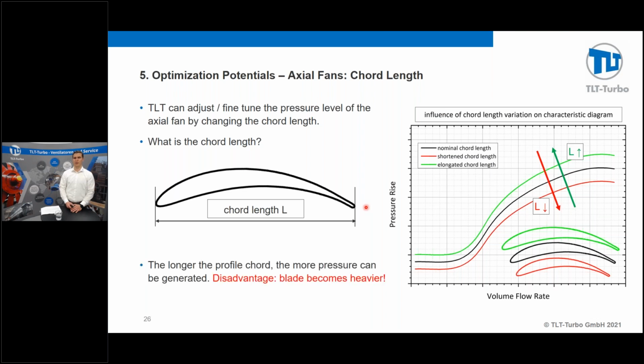I should also mention a disadvantage now. If you change the chord length, of course, the blade becomes heavier if you elongate the blade. So you need to take care of the mechanical problems which might occur through elongation of the chord length.